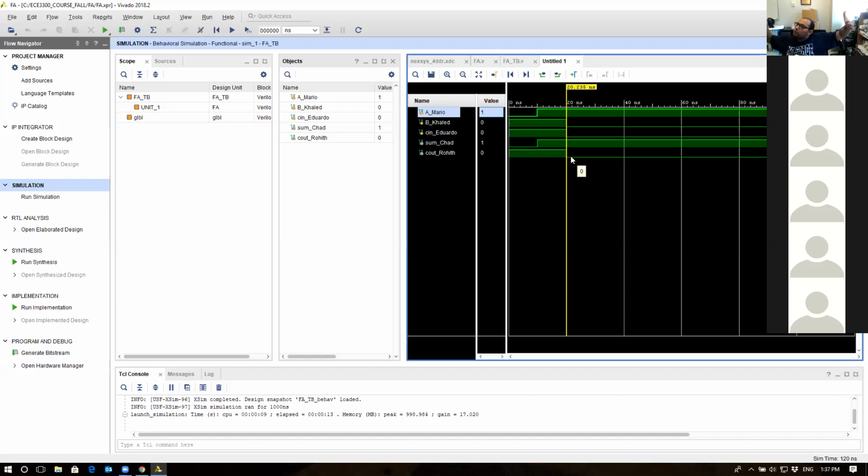If you have 32 units connected like this, the whole system has to be very slow because it's basically n times the 1 bit full adder delay. And we calculated the 1 bit full adder delay as 6 nanoseconds if everything is built with 2 input NAND gates with 1 nanosecond response delay. That makes sense?